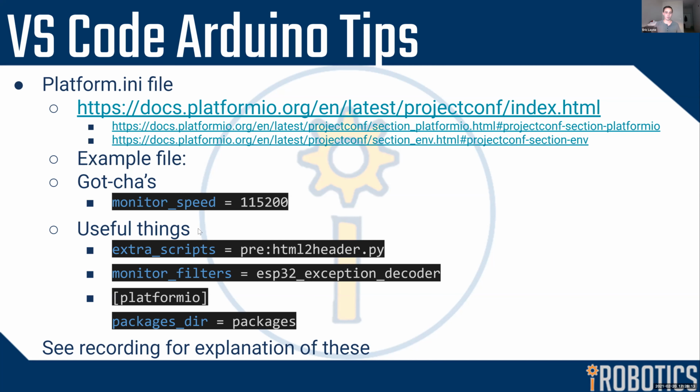A couple other useful things, like I mentioned, you can use a Python script that runs before compiling to convert HTML to a header file for C++ compilation. You can do things like, if you're working on ESP32, the serial monitor can automatically decode errors and tell you what line issues are on, if you have a runtime crash, tons of different things.